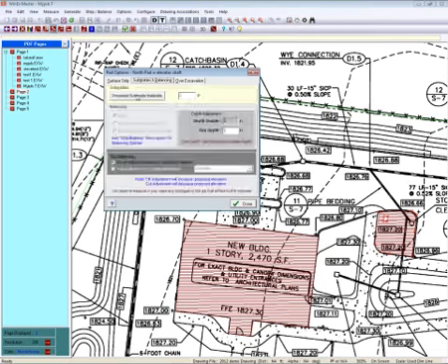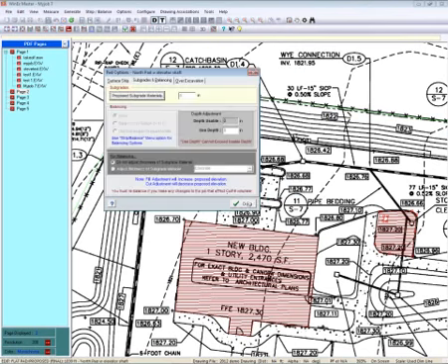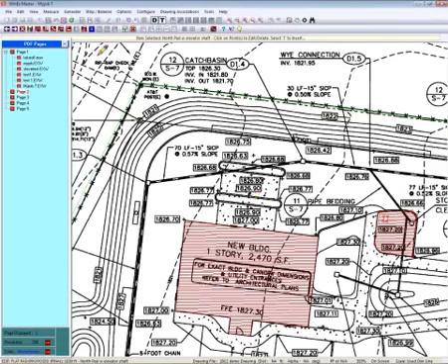And if we click on subgrades, you can see it's got the one subgrade that we put in here, the 8 inches. So if we had to add another one, we could, or edit that out, we could also do that. So anyways, that's how easy it is to put multiple pads in. And I'm going to click out of here now to get off the Edit menu.